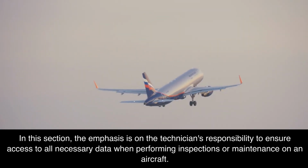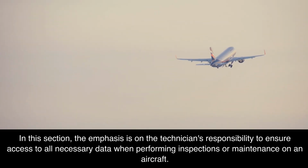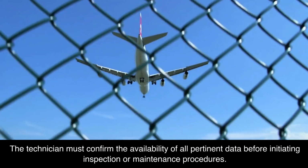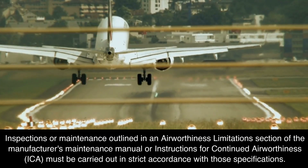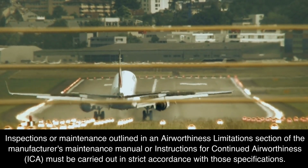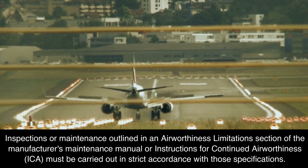In this section, the emphasis is on the technician's responsibility to ensure access to all necessary data when performing inspections or maintenance on an aircraft. The technician must confirm the availability of all pertinent data before initiating inspection or maintenance procedures. Inspections or maintenance outlined in an airworthiness limitations section of the manufacturer's maintenance manual or instructions for continued airworthiness, ICA, must be carried out in strict accordance with those specifications.